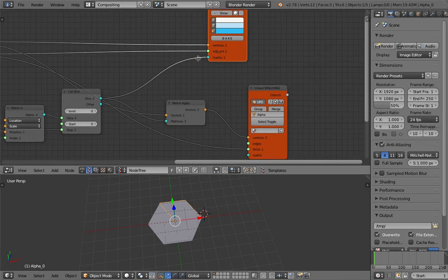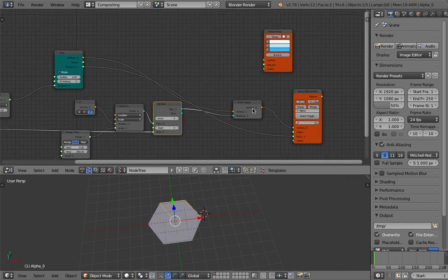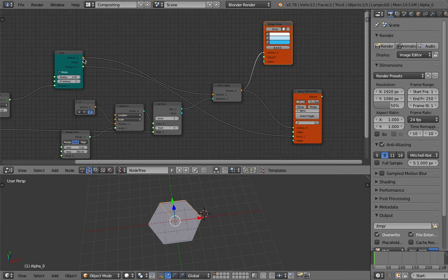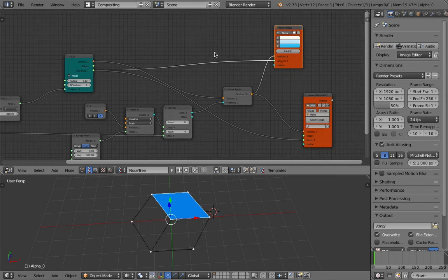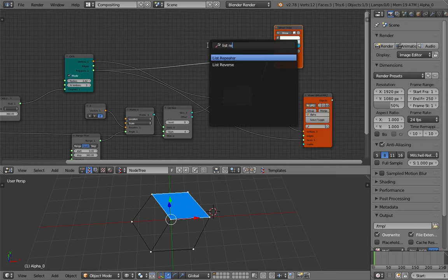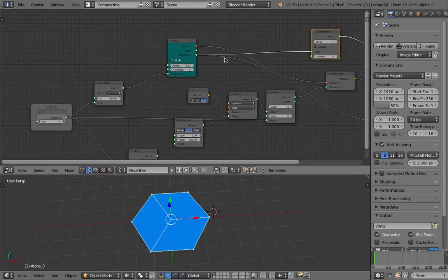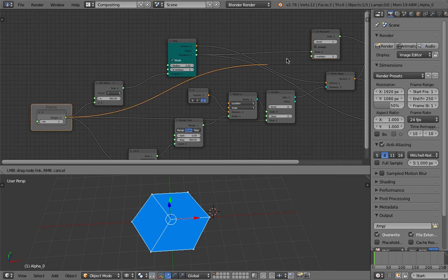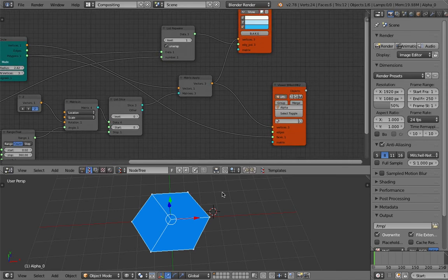But if you try to cut this and plug this guy into that guy and then polygon directly, normally it will not work. You see, it's not working properly. You need to use a list repeat, and that number should correspond to this guy. Unwrap as well. So bake.